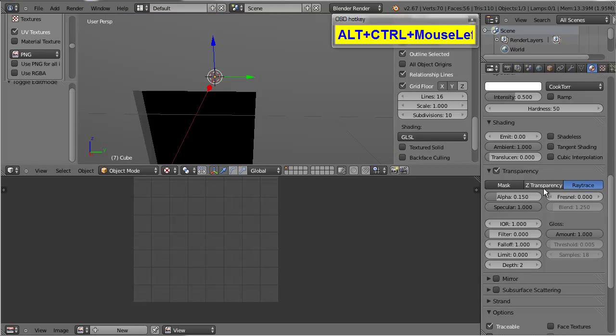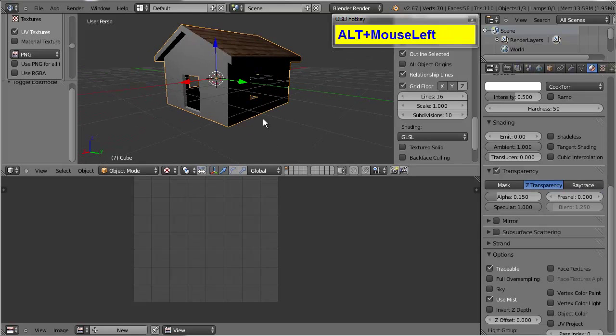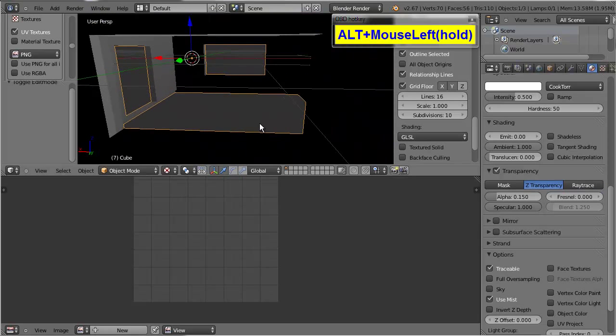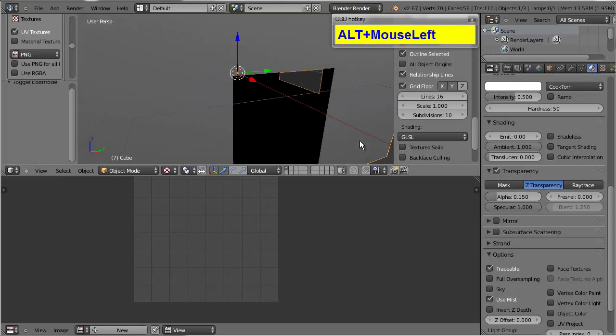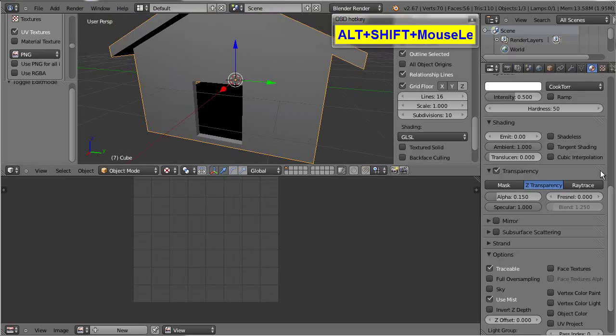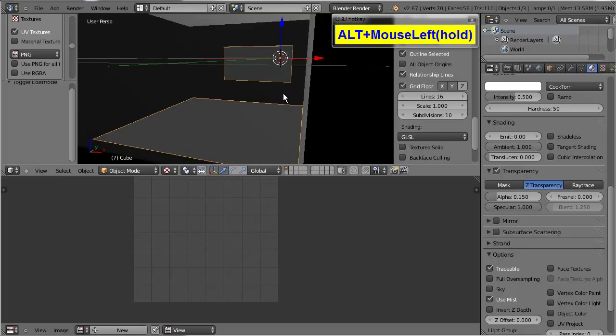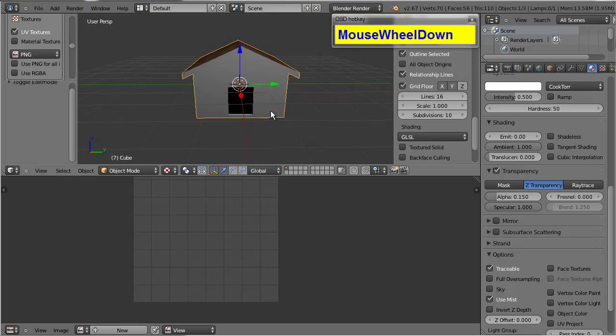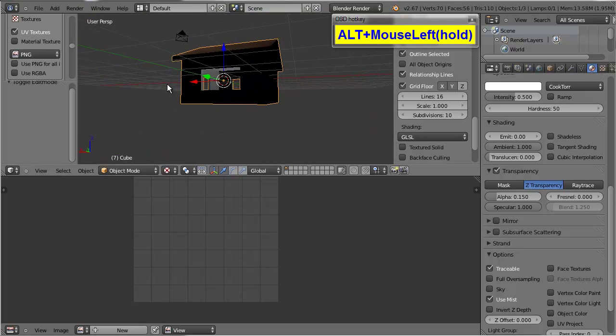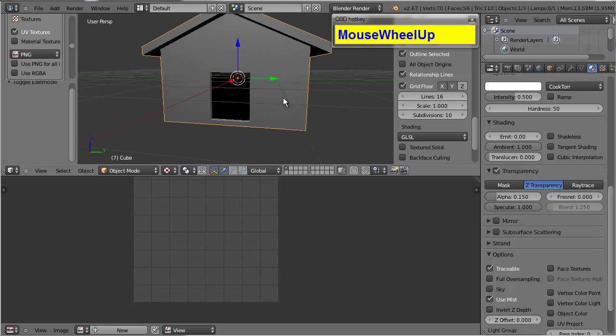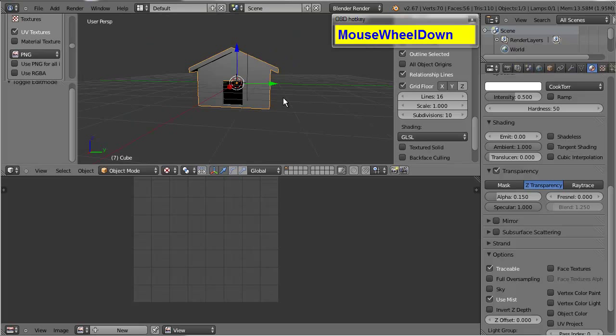And you'll want Z transparency selected there. If you want to see it in the viewport, you'll want Z transparency. Otherwise, use ray trace. Ray trace is actually a much better way of doing shadows and transparency and stuff like that. So we have the window part done, and I think that's all the texturing I'm going to do. That gives you a decent idea of how to do that kind of stuff.